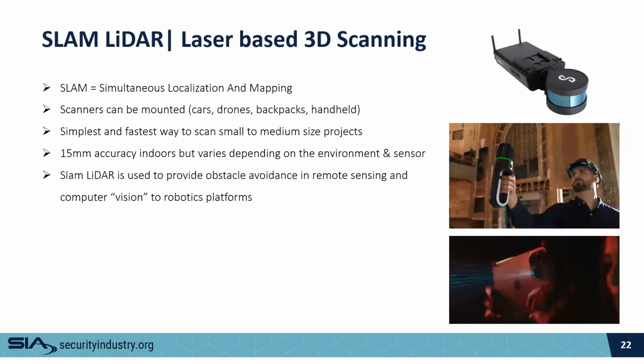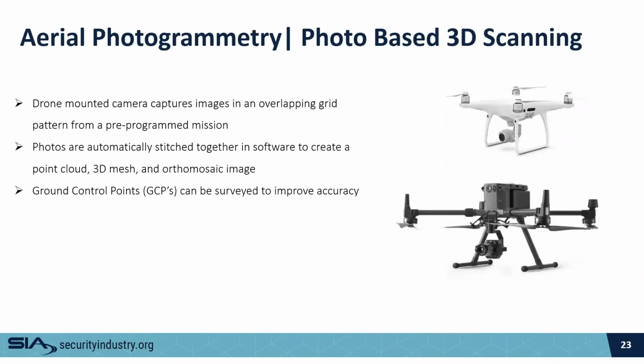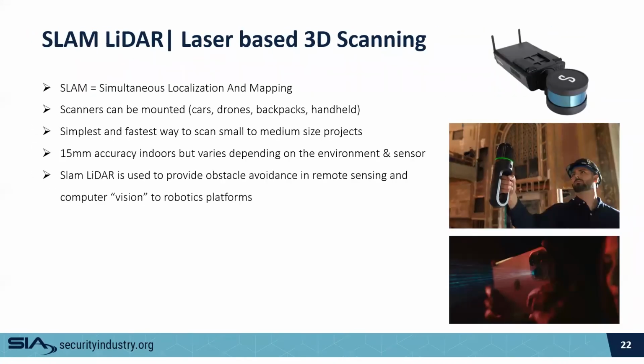Another rapidly growing technology, SLAM, which is simultaneous localization and mapping, applies LiDAR with various other sensors for us to be able to move while we're collecting the data. So these are mobile LiDAR units that are using various sensors, RTK, using IMUs, which we'll discuss in a moment, to be able to locate the position of these point clouds and scans. Accuracy is less, noise level, meaning the artifacts or the relative defects that we'll see in the laser scan, are higher, but from a practical perspective of being able to capture it quickly and at large scale, it's a tremendous opportunity.